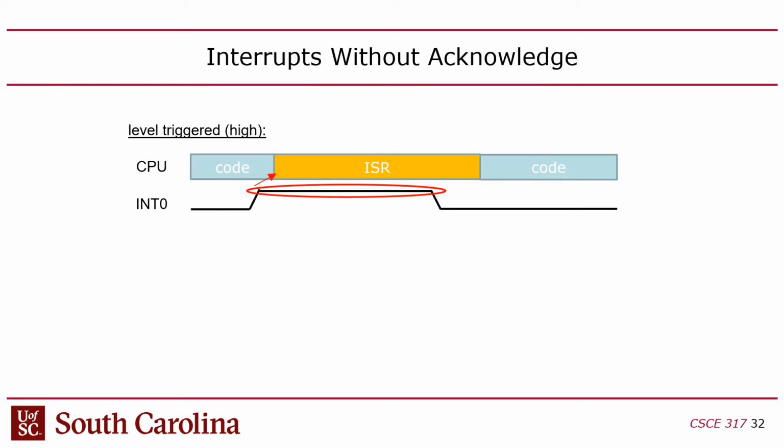Okay, so how does an interrupt physically look? The simplest way an interrupt would work would be a single wire from the peripheral to the CPU, right? You have a wire that's normally logic 0, and a logic 1 on that wire would be, hey, I need your attention, right? At which point the peripheral would expect the CPU to automatically execute an interrupt service routine on behalf of that peripheral, right? And then finish. So the CPU is sort of acting like a server in a way, and the peripheral says, I need you to service me, right? So it triggers the interrupt.